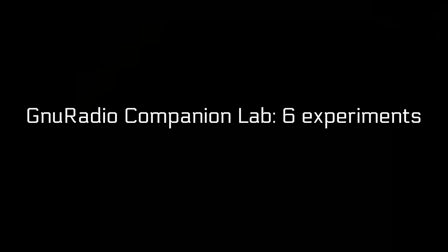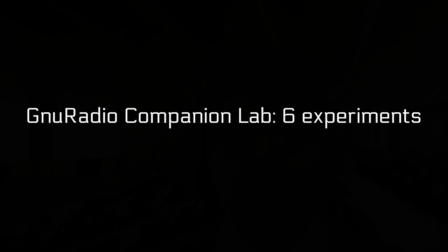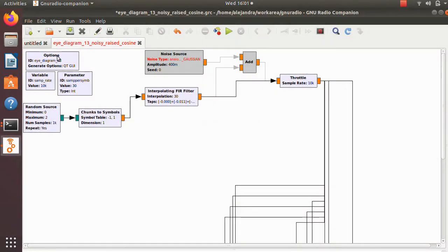All right. Let's go ahead and go into our lab. I would like you please to open the GRC file that I sent to you. So here we see the sampling rate at 10,000 hertz. We have the samples per symbol at 30 samples per symbol.